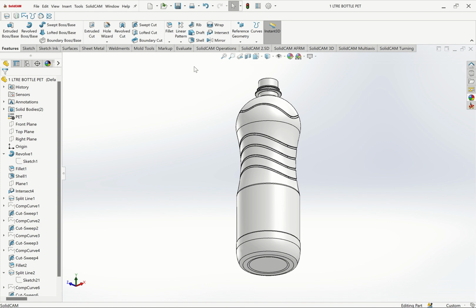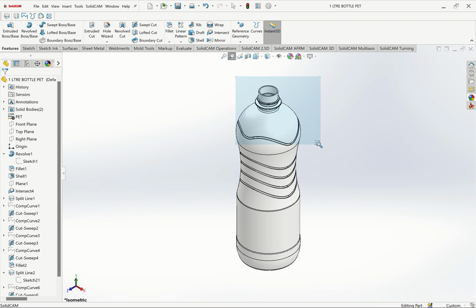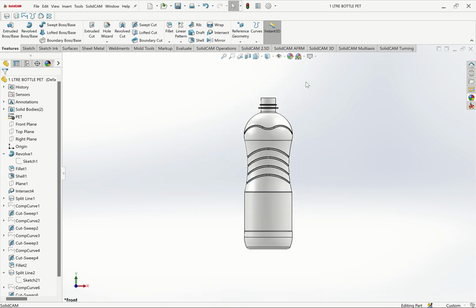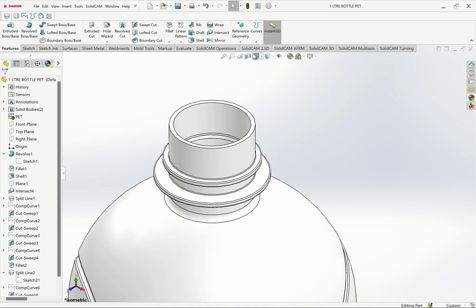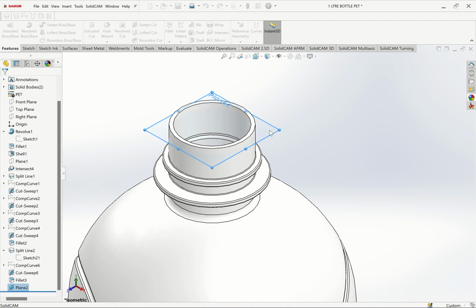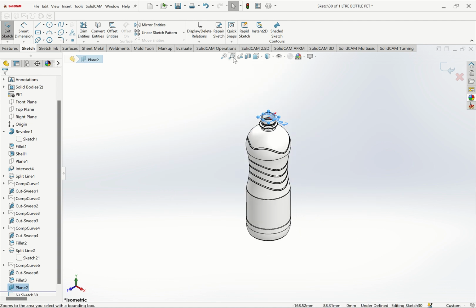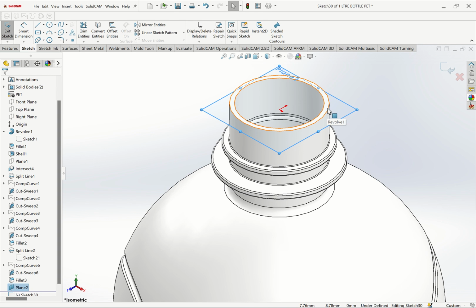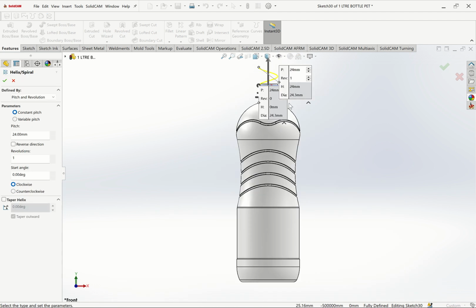You see, if it was for blow molding, I will use preform for the upper side, this preform. But if I wanted to do the injection mold, I can add the upper one. So let me add the upper one where we can hold, say 2, flip, okay. Then on this plane sketch, click Control 7. Let me show you how we can maneuver. Click on this one, then convert. Then from there, come to features, curves, helical, Control 1.